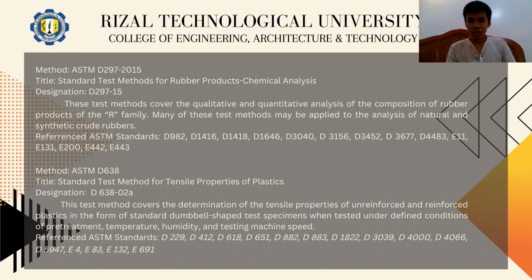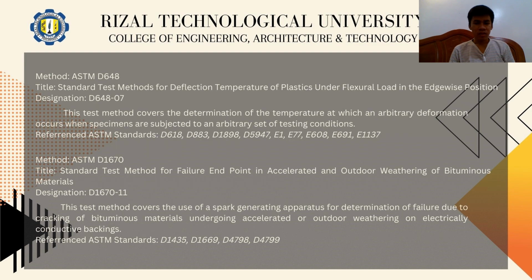However, because of the high degree of sensitivity exhibited by many plastics to rate of straining and environmental conditions, data obtained by this test method cannot be considered valid for applications involving load time scales or environment widely different from those of this test method. Next is ASTM D648, Standard Test Method for Deflection Temperature of Plastics under Flexural Load in the Edgewise Position.